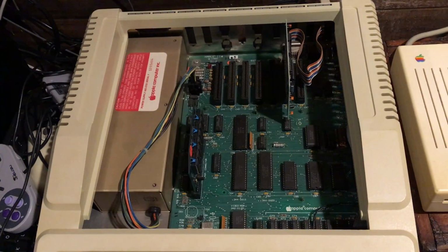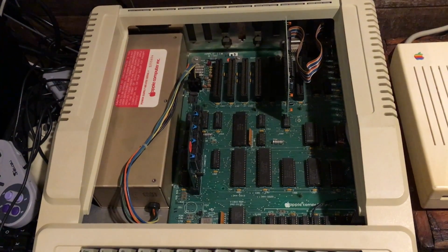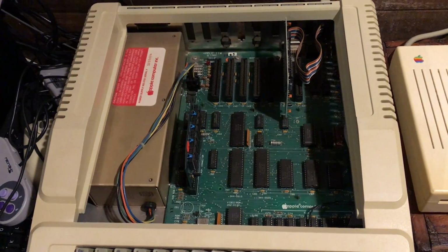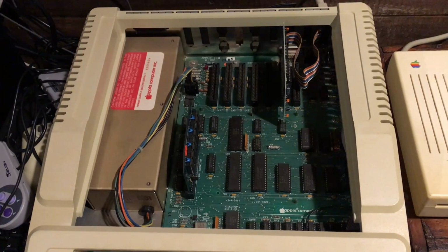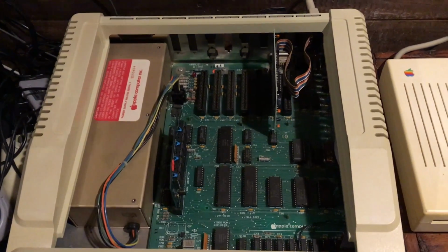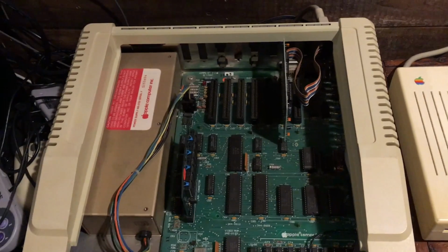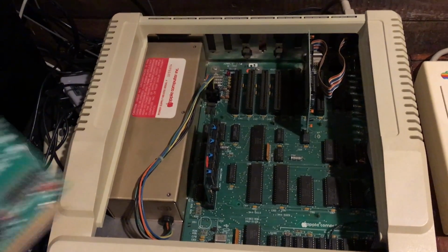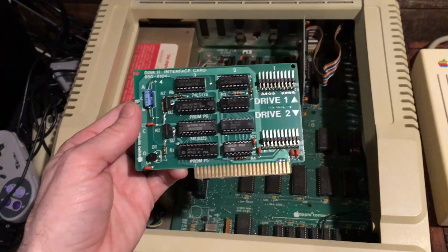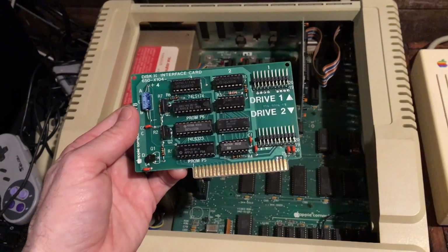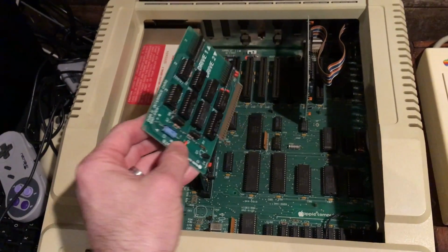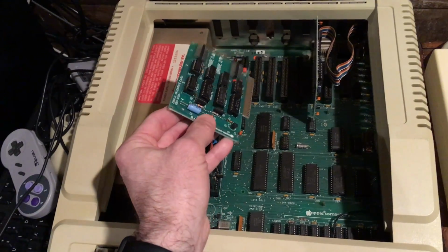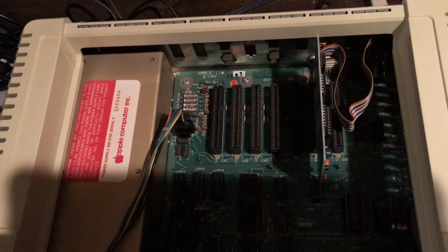I've gone ahead and opened up the inside of my Apple IIe so that you can really see what is necessary in order to operate a disk drive off of an Apple II. So you have a couple of options. If you're going to use the drives that were designed for this model that have that black front, you're going to need to add in the Disk II interface card. This is a card that fits into one of these slots. I don't know if they called them ISA slots on Apple IIs, but in the PC world, that's certainly what they look like.